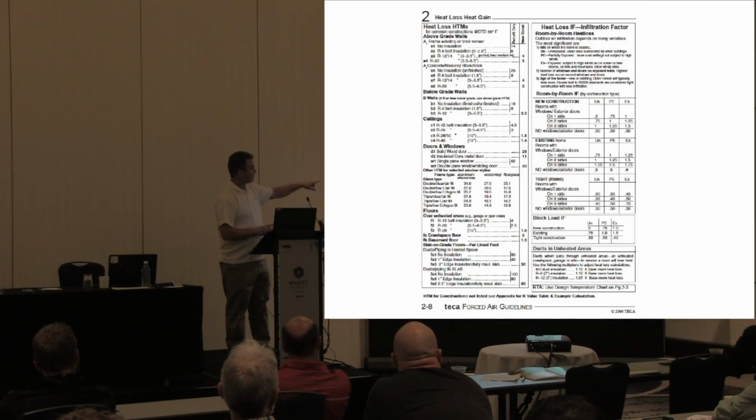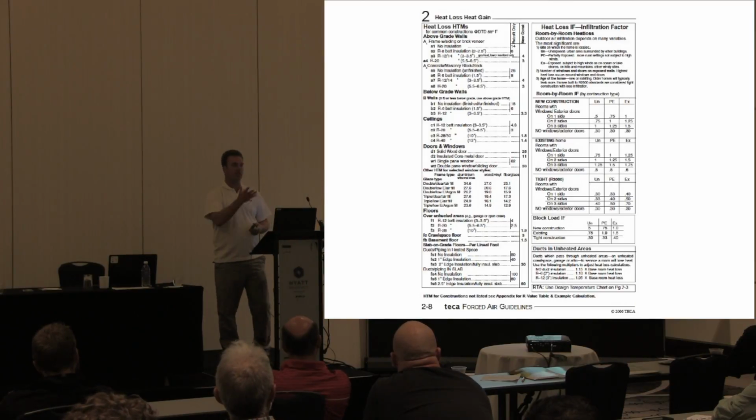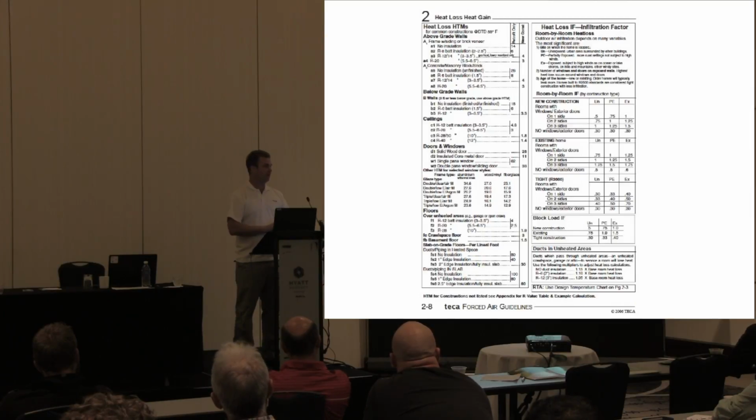Below grade walls have a different factor. It depends on what your insulation value is, which has been changing, and you're pressured to do a little bit more with the new energy code for below grade walls and ceilings. So pick it and make sure you get as close as you can to the right factor, and you'll get a more accurate number.